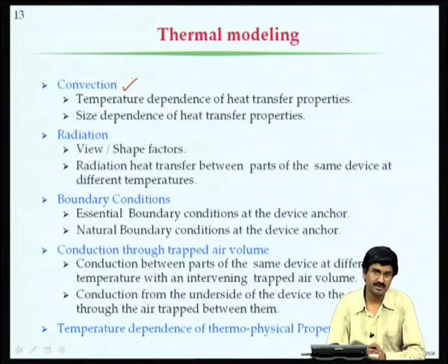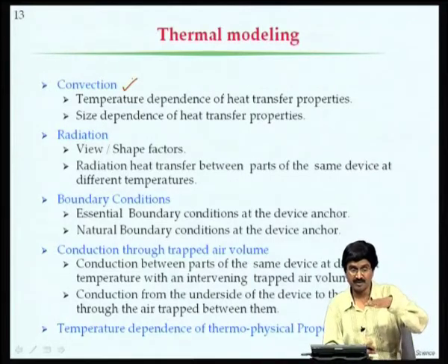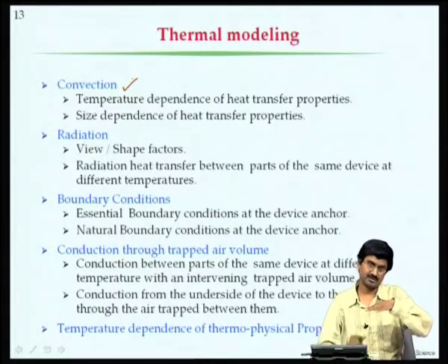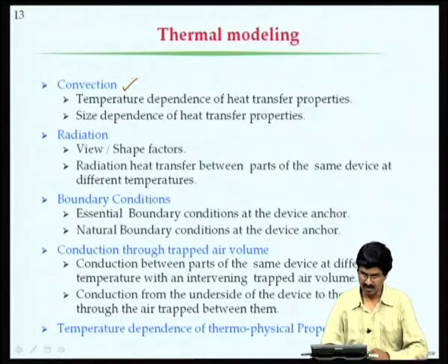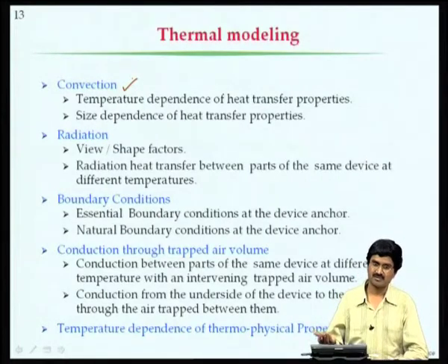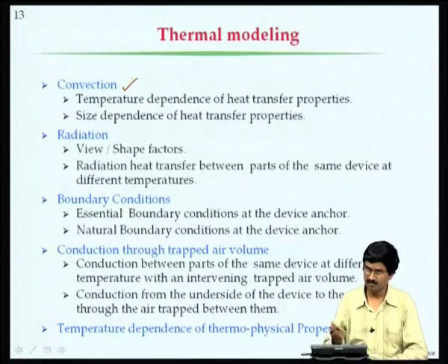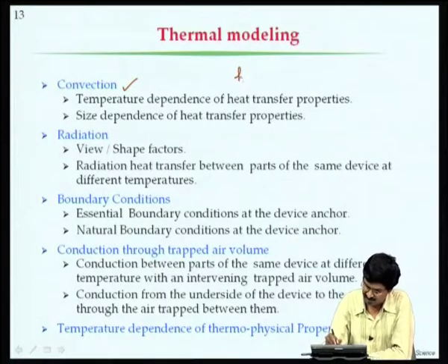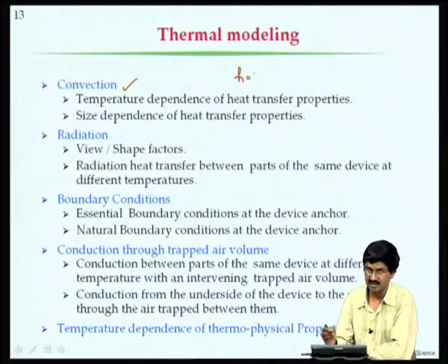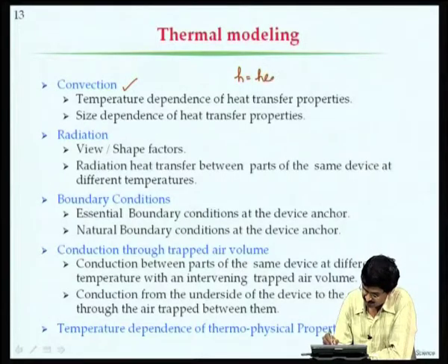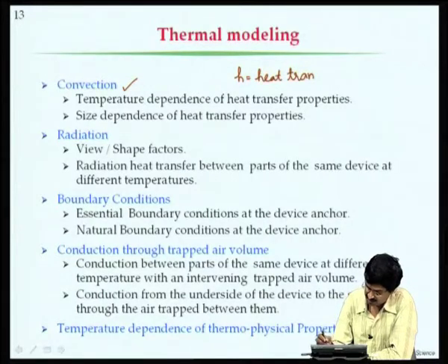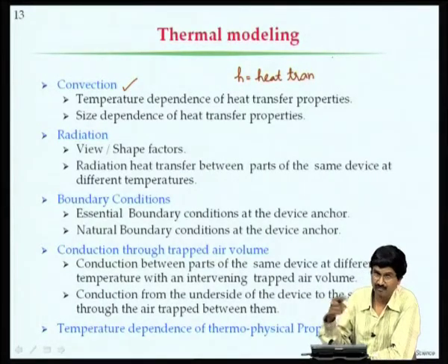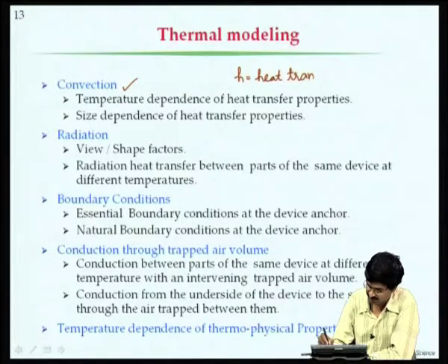When you have a structure like a wide beam, if you want to know the convection through the top or bottom surface, we have to go to heat transfer handbooks and find what is called the heat transfer coefficient, denoted with H. This can be for natural convection or forced convection, such as putting a fan and trying to cool something.